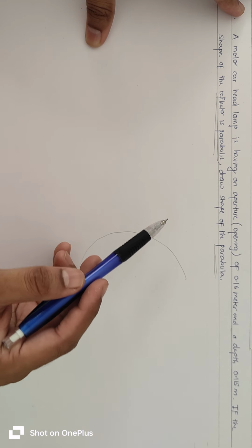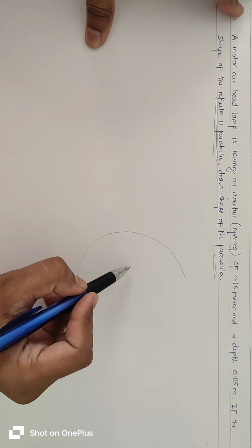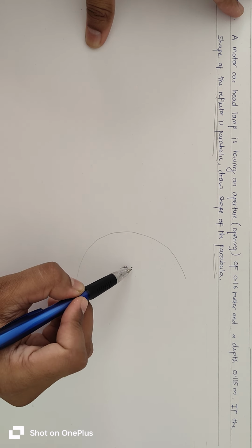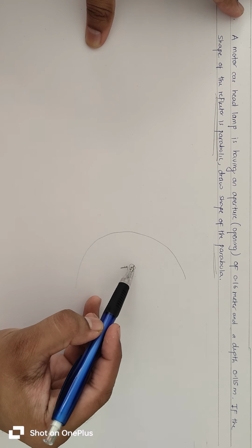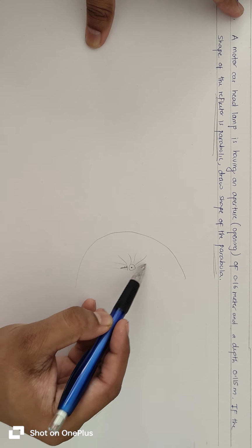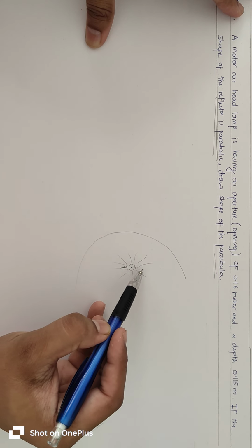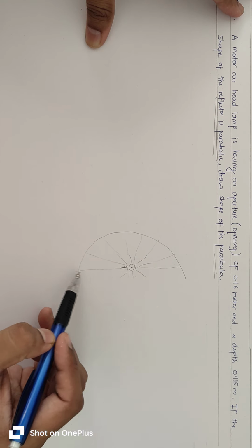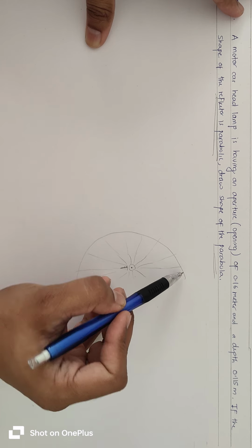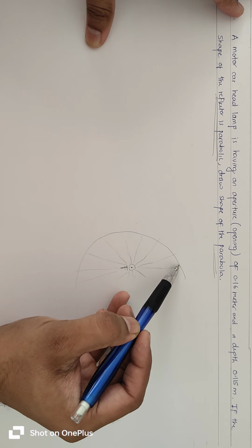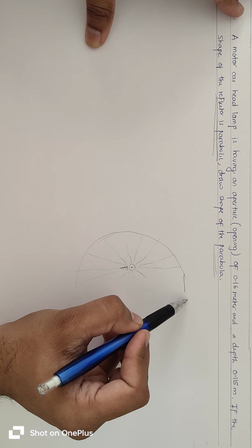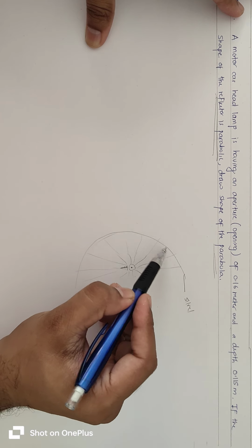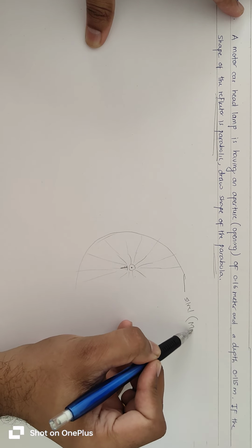The inner shape of the motor car headlamp is parabolic, because if this is a parabola and this is a focus point, and suppose this is a light source generating light and reflecting at all angles, then consider the light reflecting on the parabolic shape with the light source at the focus point. Suppose this inner shape is coated with silver, that is, it is a parabolic mirror.